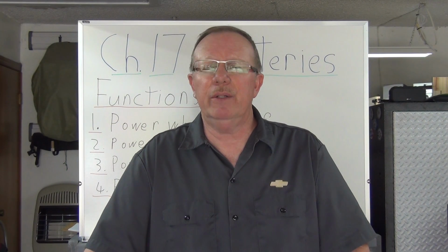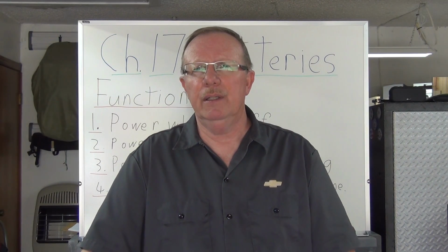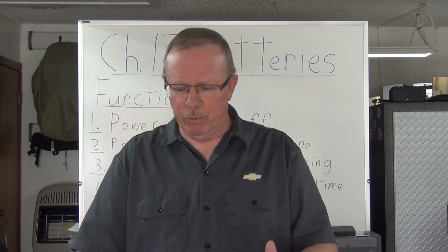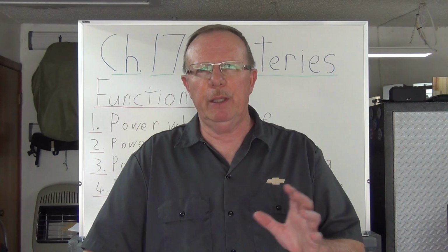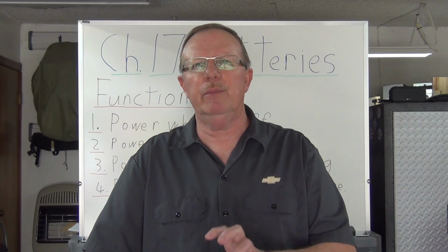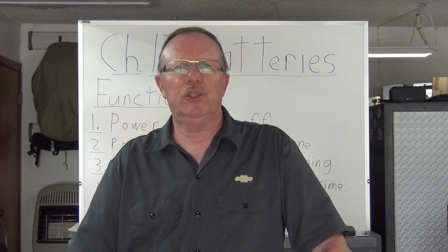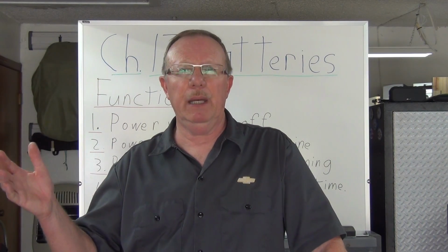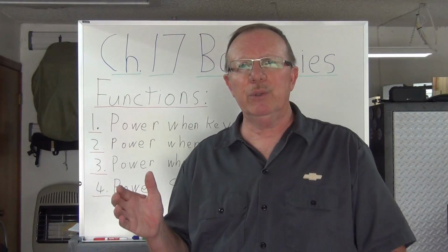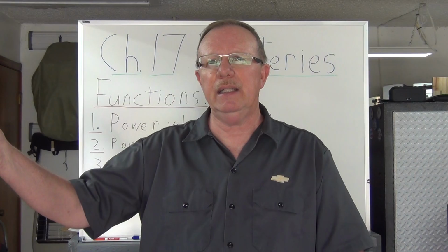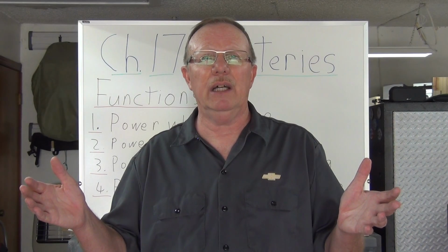Okay, the battery would charge up and it would test good, or it might test bad. It's happened a couple of times. All right. So finally, I realized, remember this again too. So I got a new battery for it, hooked it on our special charger that we had that tested batteries and charged them and all that stuff. And that brand new battery took an hour and a half of charging before it came up to specs. Okay? So I think what was happening, even though I was putting a new battery in it, that battery was not fully charged. And they drove it 10 miles back to the daycare and parked it, right? And it wasn't really fully charged, even though it said 12 volts, right?